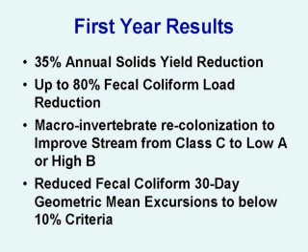In the analysis we did with this facility, we got a lot more data, and we did modeling with that data and looked at a frequency of excursion rate to determine if we are meeting the requirements of the standards. There's also a future TMDL. Right now, the stream is listed for macroinvertebrates. There will be a future TMDL that'll say improve aquatic biology to some level.